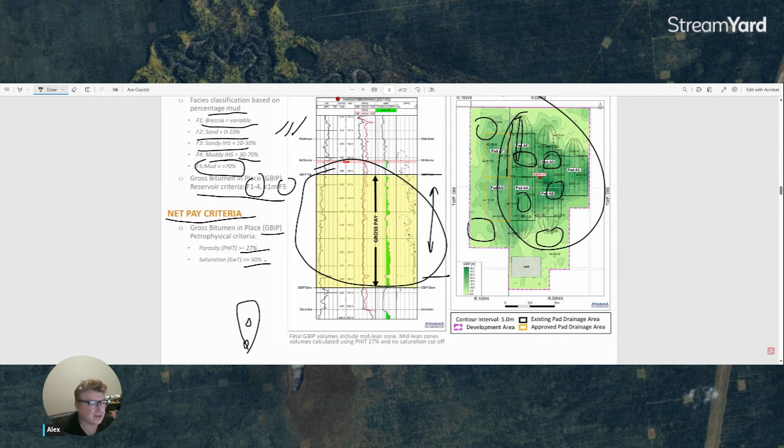The oil sand is really a deposit containing heavy hydrocarbons, in this case bitumen, in the intergranular pore space of sand and fine grain particles. That's why the fluids are able to flow through the sand and be produced at the surface. So the typical oil sand comprises approximately 10 weight percent bitumen, 85% coarse sand.